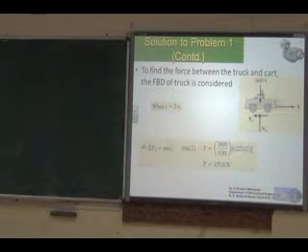Now we draw the equilibrium diagram for the truck only. The load of the truck is there, then the frictional force Fa, then you have the towing load coming from car A and car B, which is considered as T. Like tension in a cable, the towing load is what the truck has to pull. The Fa is acting in the forward direction, that is 160t, small t. The capital T is the towing load, which is opposite to Fa.